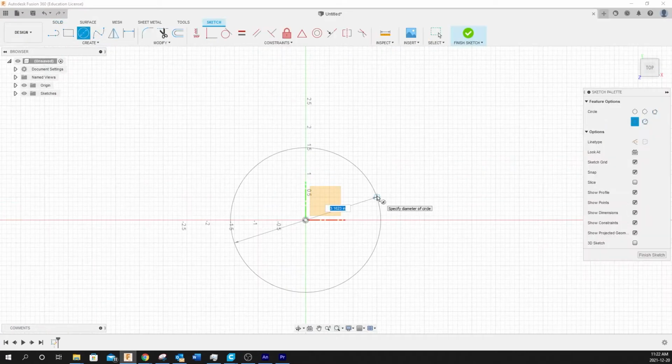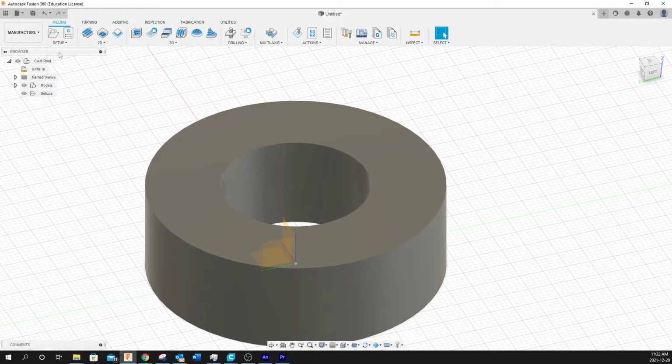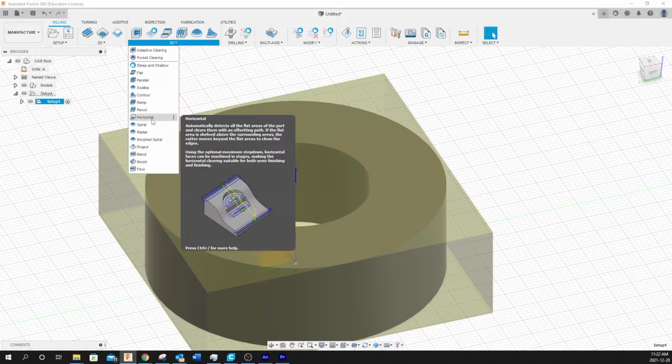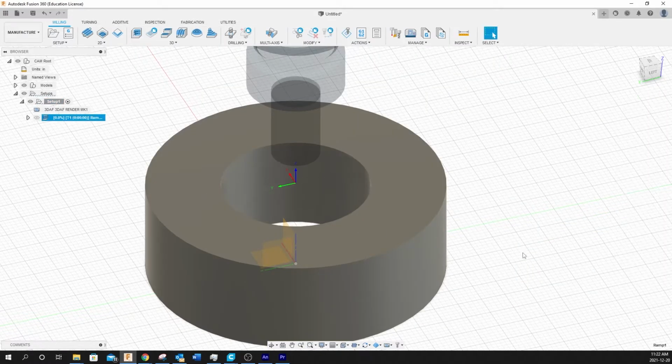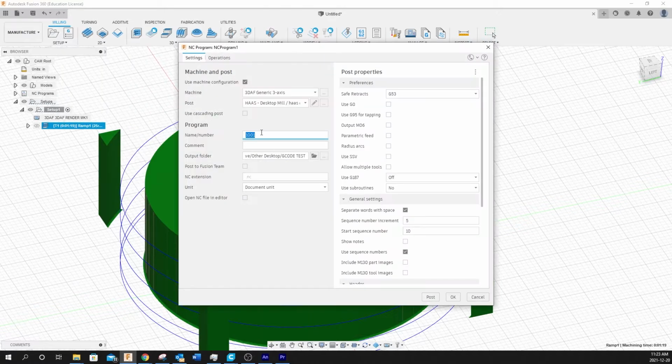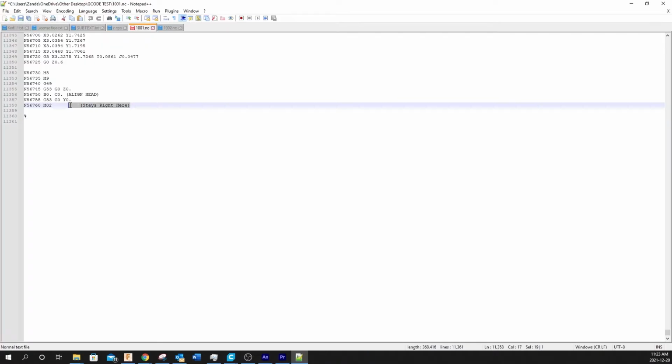And now on to end codes, M02 and M30. End codes represent the formal end of a program. M02 ends the program and just stops at the last line without recycling to the top. And M30, which is much more common these days, ends the program and brings the cursor all the way back up to the top of the program.